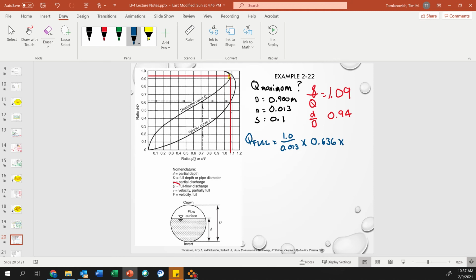So that is 0.9 divided by 4, which is 0.225, because remember, it's D over 4. It's cross-sectional area of flow divided by wetted perimeter. Because the pipe is full, we know it equals D over 4. So just remember what hydraulic radius is. It's that definition.